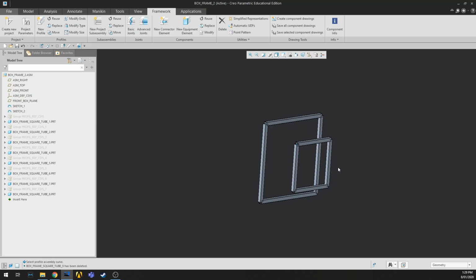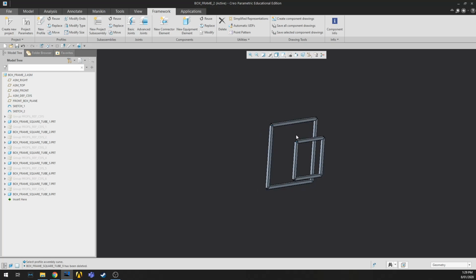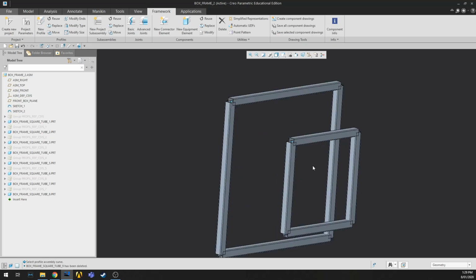Also, when you get tubes laser cut, the laser cutting company can etch all or part of those tube names onto your tubes for you. You can also do things like put in points that you want etched onto the outer dimensions for where to line tubes up. Some pretty fancy things like that that make the assembly process really nice.